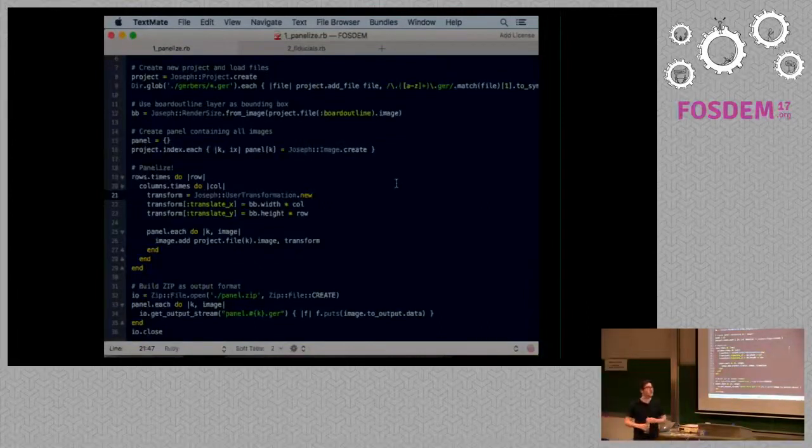Right. What about the mouse bites, instead of V-score, adding them? You have basic drawing functionality. Use this. Just draw a few lines. What we do is we usually mill the PCBs, so we draw a milling pass. Right. But creating the milling pass is another topic. But adding the milling pass to a Gerber layer, that's the task of Joseph. One question over here. Yeah.